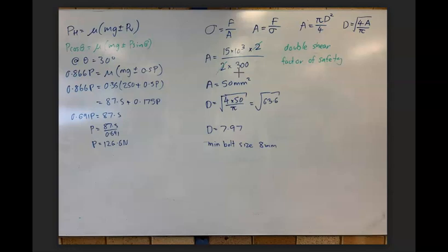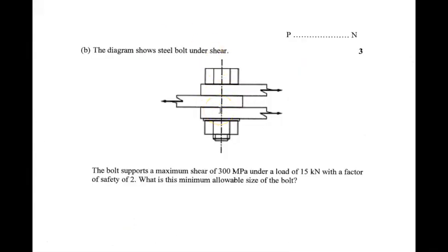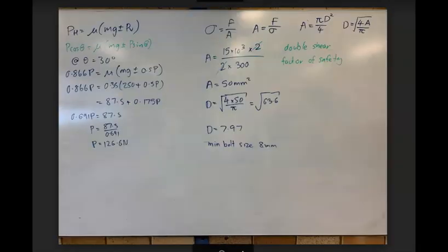I had a student ask, I don't understand why there is twice the area, because what we're doing is we're actually cutting through the bolt twice. It's the same as if we had the bolt being joined, we had two bolts. We're double the area out of this bolt. The bolt is working twice because we're getting twice the area effectively out of the bolt.